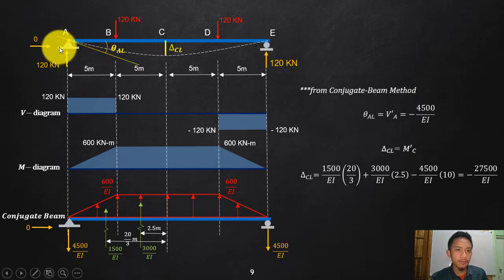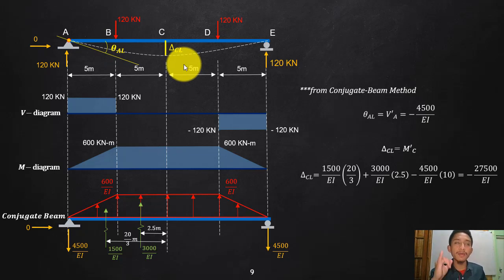Okay, so this is simply supported, a pin and a roller. So if you apply here your 120 and 120 load, this could be my deflection here, and of course, how will we get that one? That is where you will be using what we recall as the moment area or the conjugate beam method, or if you are used to other methods, then why not?